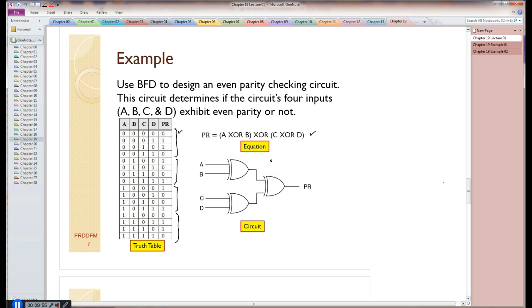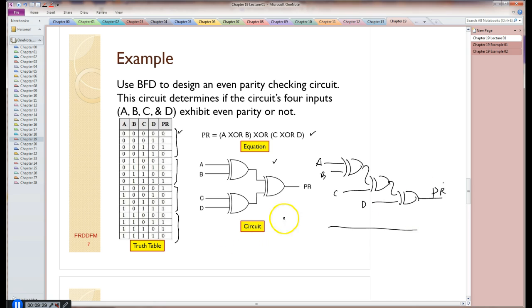So this circuit is not the only way to implement this. There's actually a certain magic with XOR gates and XOR functions, however you want to put it, such that I can do this a little bit differently, so I'm going to do that real fast. So this circuit is another way to implement this circuit. They're functionally equivalent. The only difference between these two circuits is I have some parallel action going on in these two gates. Overall, there's just 2 levels on this. So this represents 1 level, this represents the 2nd level.